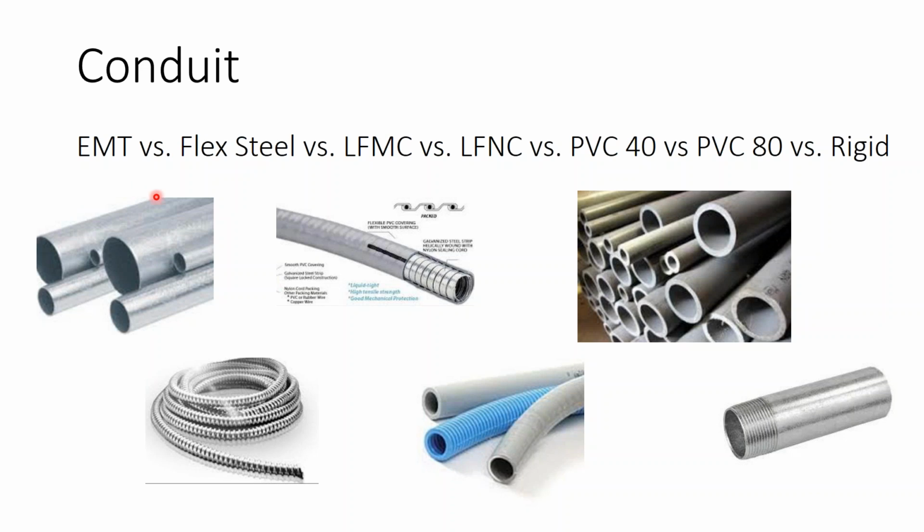And that metal housing for DC wiring is simply to give it some additional protection, where ground faults with DC are more likely to cause fires than with AC. And so they want to give it a little bit more of a rigid protection to prevent critters from gnawing on the cables. And so metallic flex conduit should be sufficient inside a battery room, except that it's subject to corrosion. And so where you have a battery that does off gas, it's best to use the liquid type metal flex conduit inside your control room.